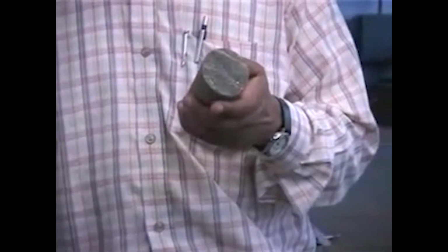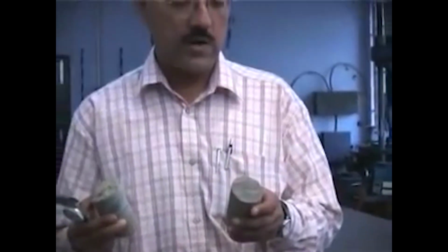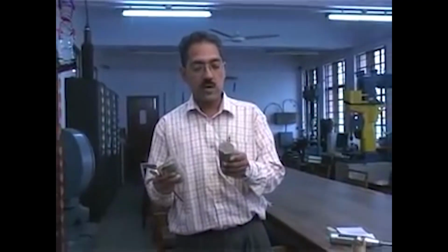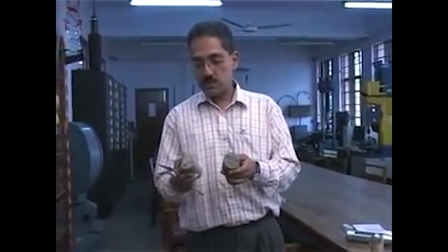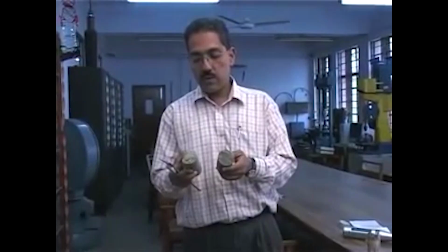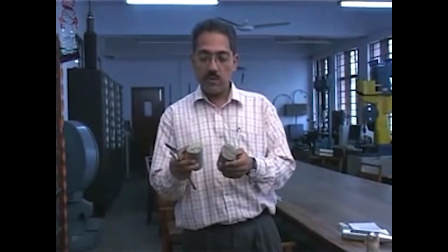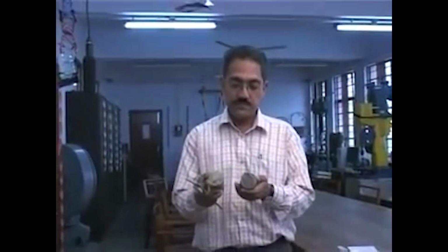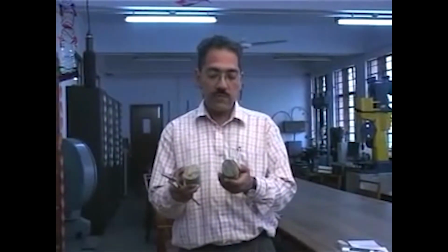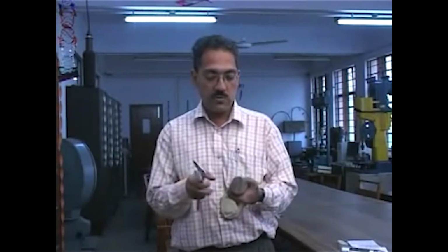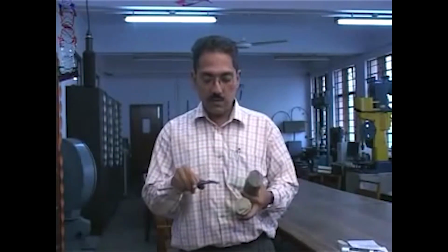So if you recall, the point load index is basically point load divided by square of the diameter of the sample. So we need to find out what the diameter is. Although both of these samples were obtained from a drilling investigation using NX bit, so we know roughly the diameter of the sample will be 55 millimeter, we need to take a careful measurement of the diameter.